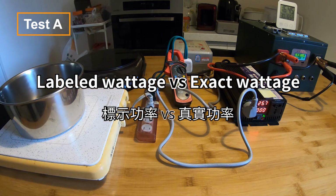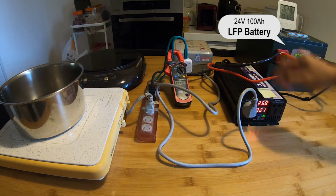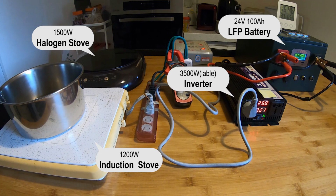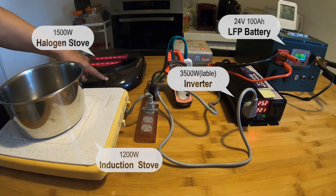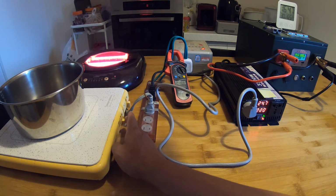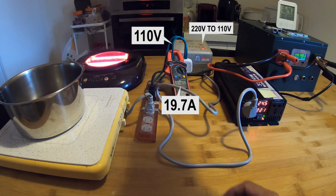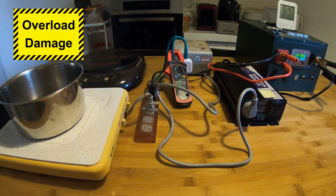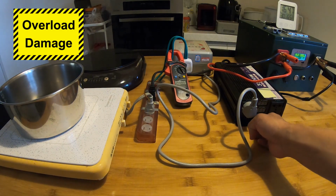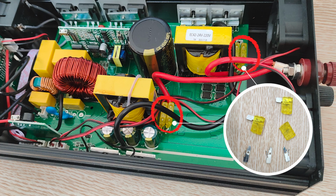Test A, labeled wattage versus exact wattage. Powered by a 24-volt 100 amp-hour lithium iron phosphate battery, using a 3500-watt inverter, connected to a 1500-watt ceramic stove and a 1200-watt induction cooktop. After turning on the maximum power of the ceramic stove, adjust the power of the induction cooktop. The output AC current is increased to 19.7 amp. The inverter is damaged due to overcurrent and cannot be powered on. We dismantled the inverter and found that all 4 fuses were blown.